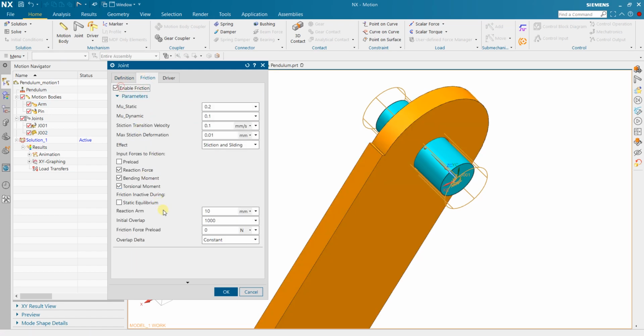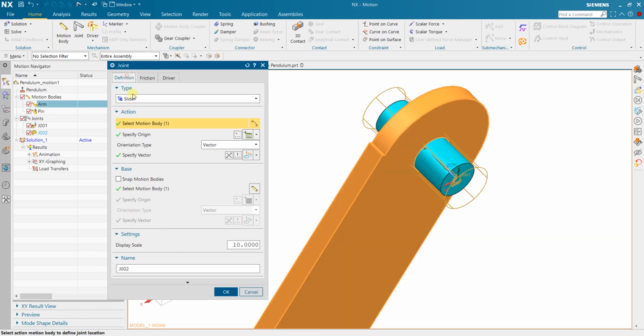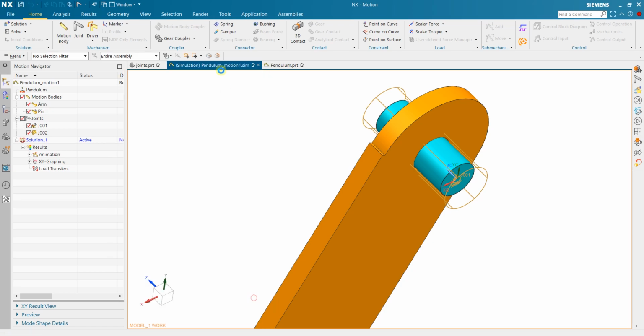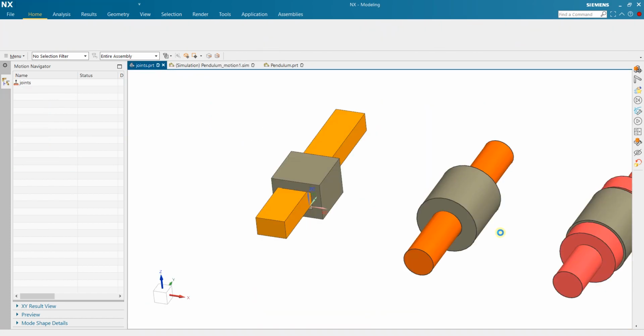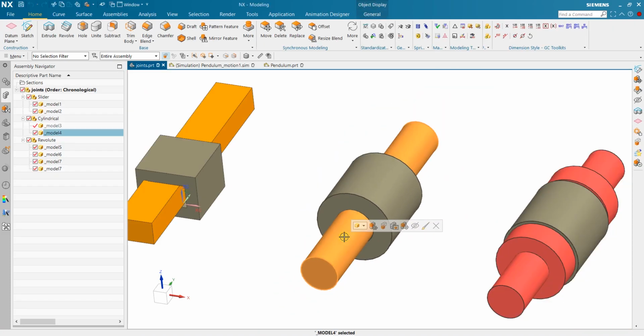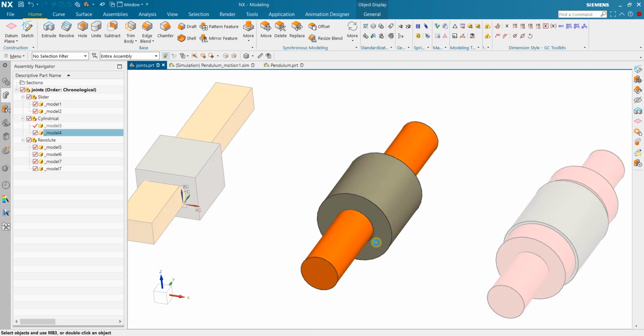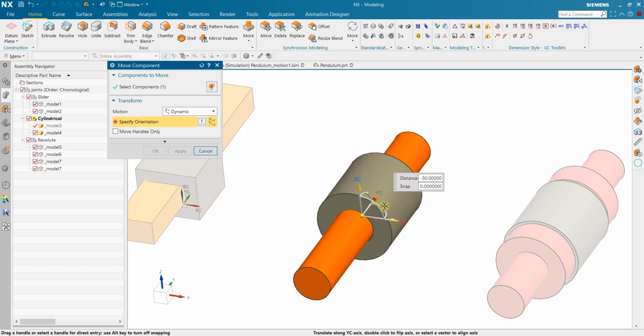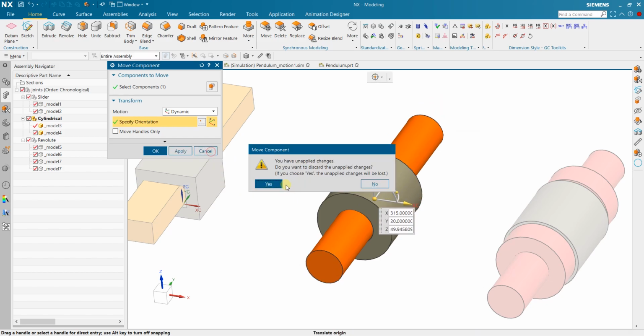For a slider, the options are very similar, and cylindrical as well, very similar options. And you can see here the one option you have is limiting maximum force, because not only do you have torque being applied on a cylindrical part here, you also can limit this kind of force. So after some force, it will move without any resistance.